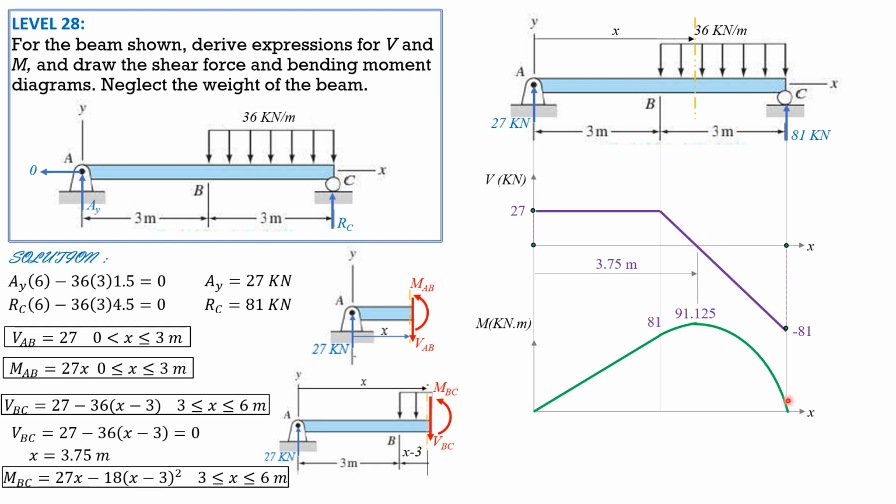Then the slope here is negative 81. The reason why it is concave downward like that is because the ordinate of shear decreases from positive to negative. So the slope also decreases from positive, then 0, then negative. So that's the description of the tangent to the moment curve.